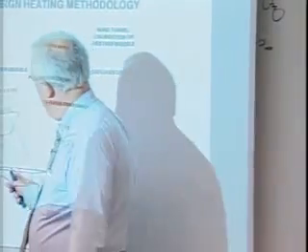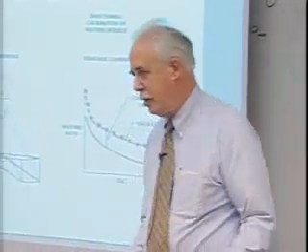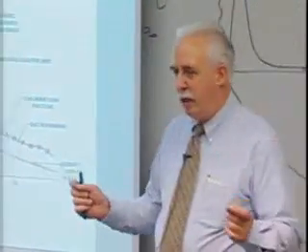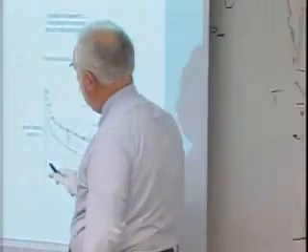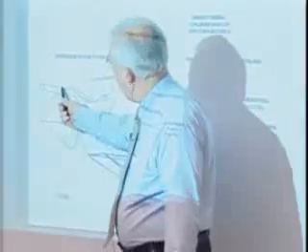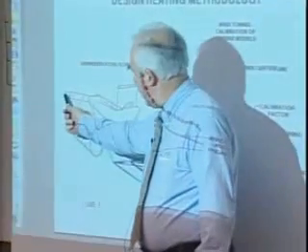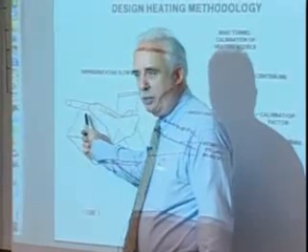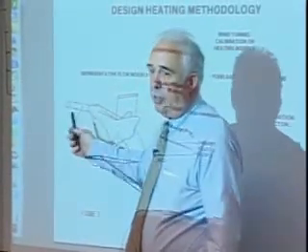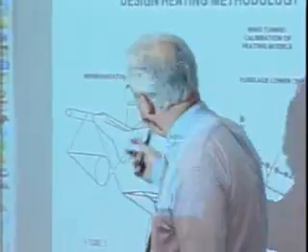Now, the way this was modeled, when we started, we didn't have computational fluid dynamics. The design methodology used to actually design the system was to model the flow. Obviously, up front here it looks kind of like a sphere, and so I calculate the heating on a sphere. I go into a wind tunnel and look at the actual data and relate that and say, oh, well, that's kind of like a sphere of 2-foot radius. Okay, so that's my heating there.